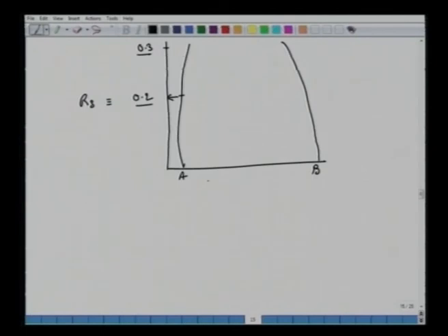So again we have this R stage in equilibrium with the extract phase from that stage. So again here we have to do this exercise. We find that tie line which connects this raffinate concentration at 0.2. So if you do this, you have the equilibrium Y versus X diagram from the same information we had in the beginning of this lecture, in the beginning of this exercise.